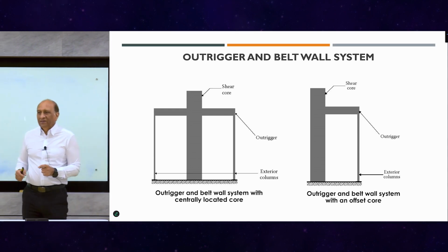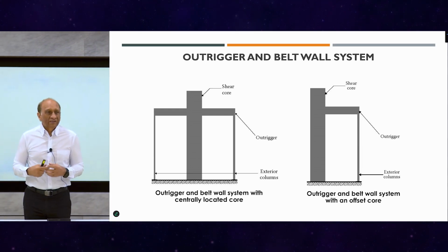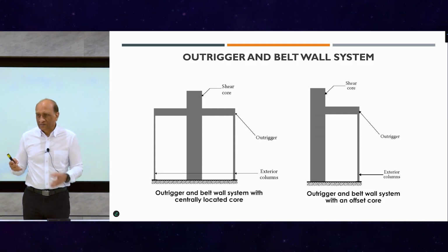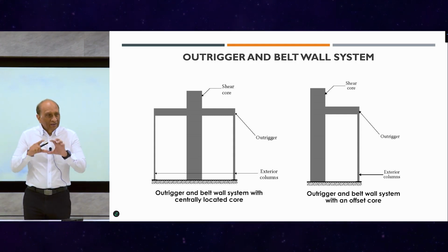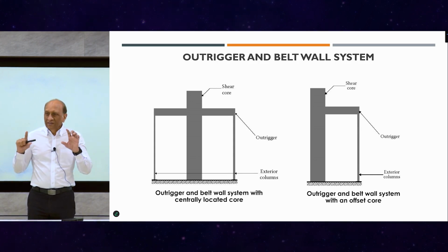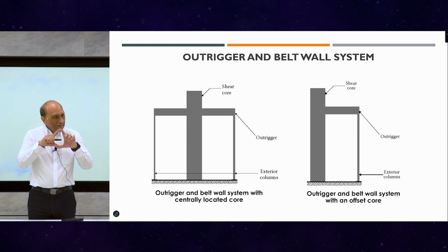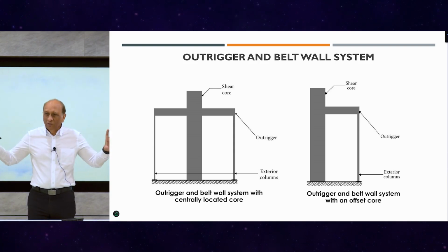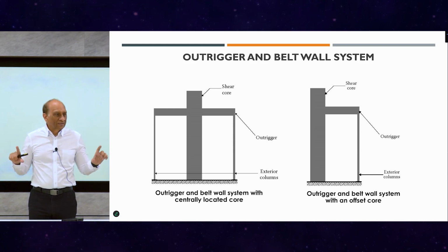Most commonly, they are used where we call the service floors. So every tall building, especially hotel or office, they have a service floor where they put all of these services like the generators, the air conditioning systems, the electrical systems. So they normally take one floor away and they put all the services there.